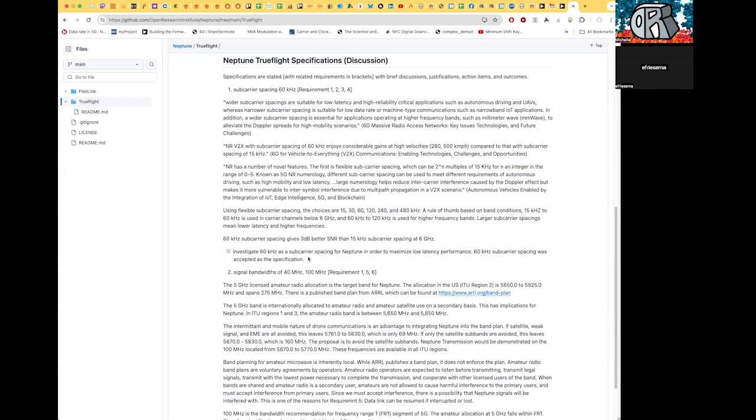The numbers work out. It's achievable with the FPGA dev stations we have, and that leads directly into the signal bandwidths proposed for the chip that was picked to support FlexLink. The maximum transmit bandwidth is 40 megahertz. It's designed for mobile devices. It's the ADRV9002. I'm really happy with it. It's paired up with the ZCU102, which is an UltraScale Plus Xilinx chip, very capable. We can do all sorts of amazing things with this combo in the lab.